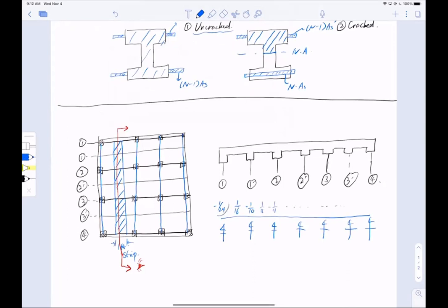This moment, if I really want to draw it out, say for example, this minus 1/24, I'm going to use blue here. If I want to draw the moment out on the section here, the moment is actually negative, so it's the other way, like this sign, and this is what it is. Omega u L squared. You see this moment? This moment looks like that.